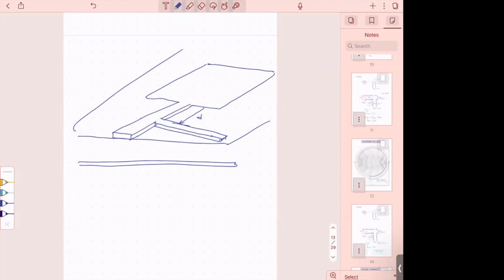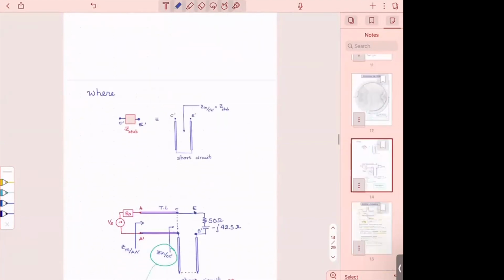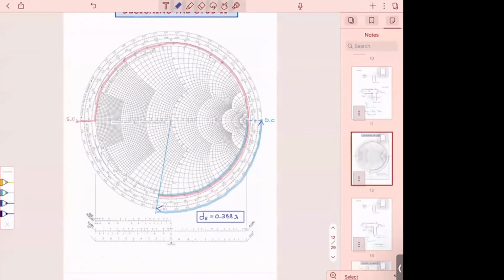You know what's going to happen with the stub? It's going to start radiating because it's as long as the antenna. It's going to interfere. A lot of times people will bend it, but they don't want to hit something this long. You always try to keep your stubs short. So on the basis of that, in your design, you say, well, that's too long. And I can see on my chart that I can have an open circuited stub, all right, which can be a lot shorter.